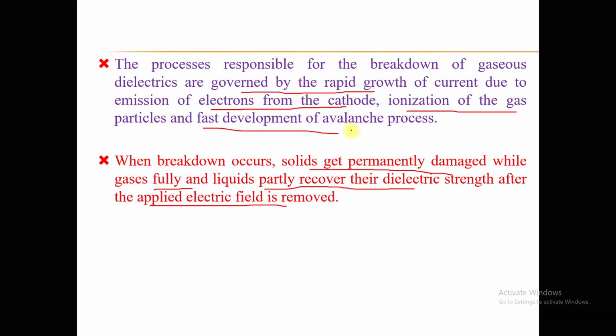So in case of the solid dielectric materials, breakdown may occur over the surface, so that is known as a flashover. In that case, there might be some damaging effects of the spark that we can usually see on the occurrence of the spark. So that phenomenon is known as a flashover.